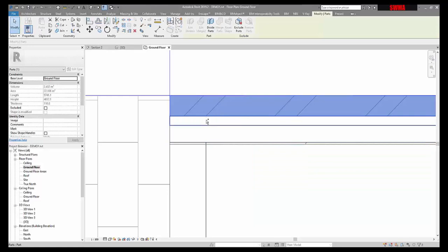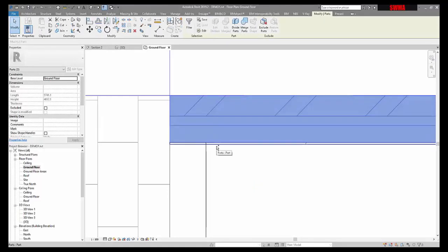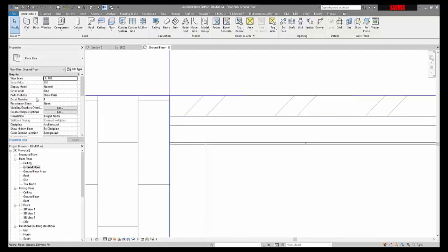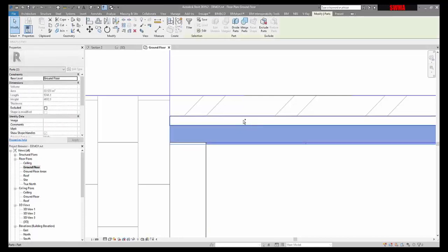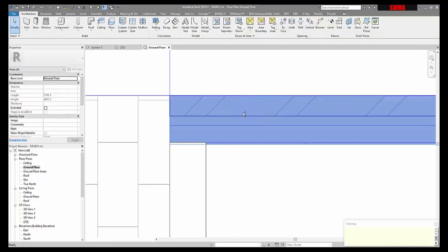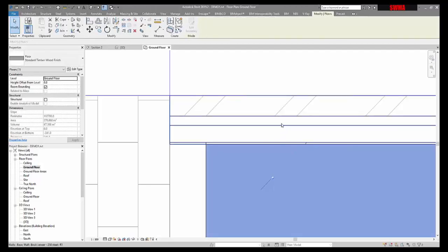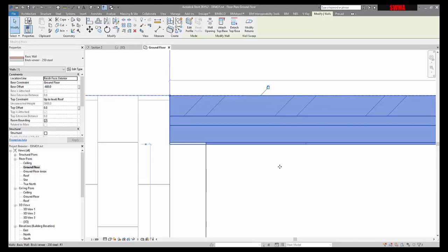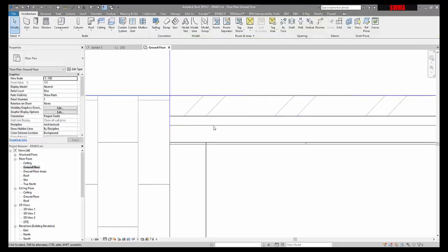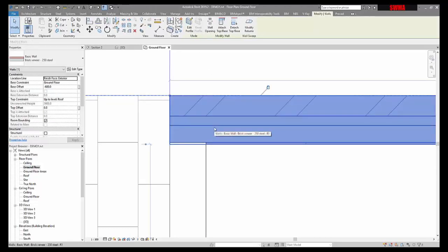So if you do need to get rid of these parts, you can select them. Oh, by the way, if they're not displaying, you need to have here parts visibility, show parts, if anybody's following along. That's parts original, that's show parts, that's show both. You can actually just delete them out. So we'll just delete them out here. That's fine. All associated parts are deleted. Now we've just got back to the wall. There are other ways to do things here, but I'm just doing it pretty simple.